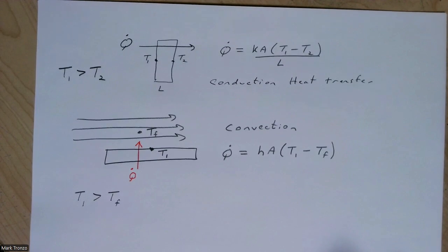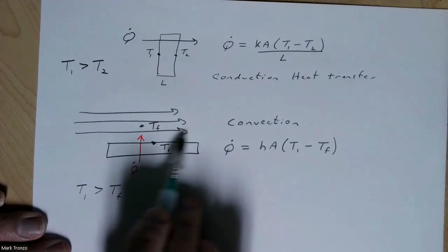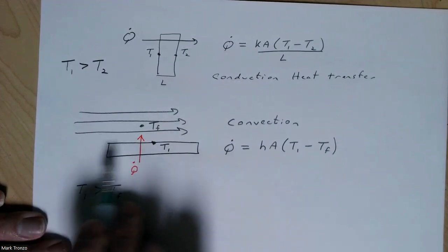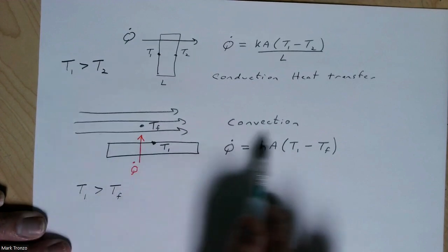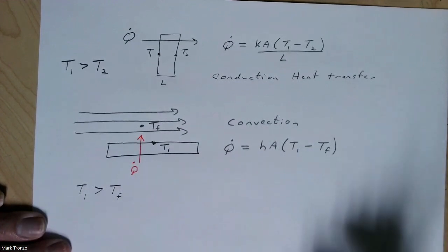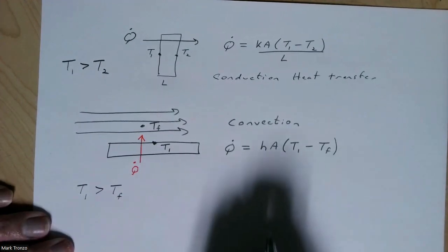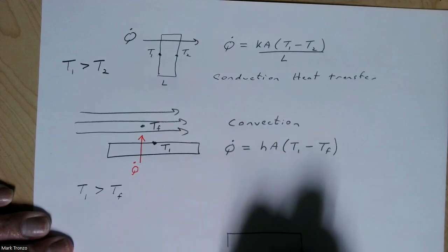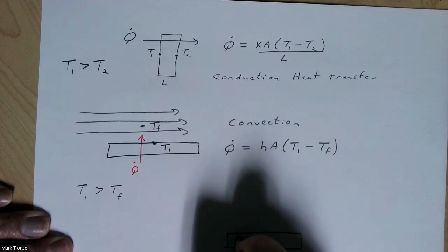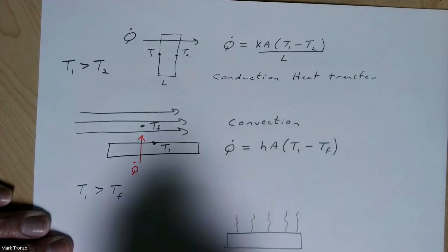Again, we can have forced convection or free convection. Forced convection, again, will be the case when maybe some air is being blown over the surface or some liquid is running over the surface. And then free convection is just when it naturally flows, even when there's no flowing air or flowing liquid. Well, let's say it's stagnant, but because of buoyancy, there's going to be heat transfer.